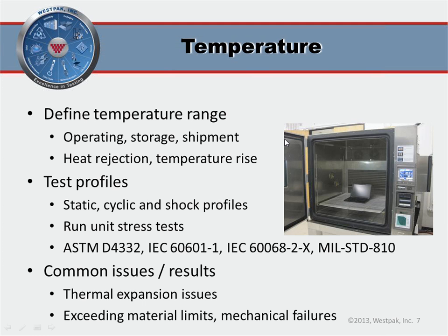For our laptop, maybe these two operating conditions, 5 and 35 degrees C, would apply, and then we'd want to cyclically operate our laptop, have it turn on and off, go to full tilt and idle to try and stress all the internal components. You might do a cyclic test, so cycling between extreme conditions of hot and cold. This will expose issues with different coefficient of thermal expansion with your materials.